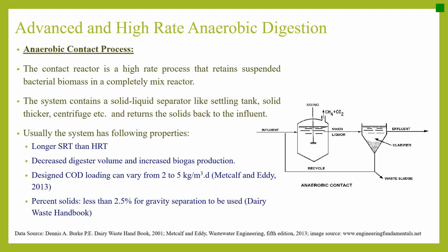Anaerobic contact process. The contact reactor is a high-rate process that retains suspended bacterial biomass in a completely mixed reactor. The system contains a solid-liquid separator, like a settling tank, solid thickener, centrifuge, etc., and returns the solid back to the influent.